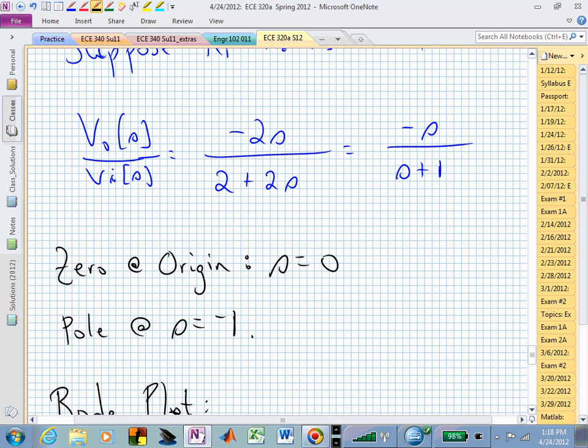And what do I know about the pole piece? We have to worry about that one turning on and turning off, don't we, in terms of its slope? How much phase will that pole ultimately contribute? It'll give us 90 degrees downstairs, so it at most will give us -90 degrees at high frequencies.